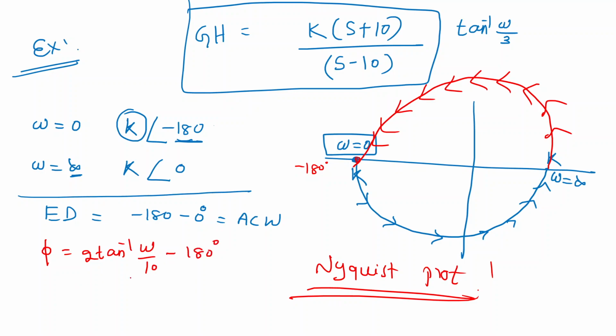Yes, sir. Now equate it to minus 180 degree, because we have to find the omega value at which the angle will be minus 180 degree. In all the cases, this is the definition of the phase crossover frequency.